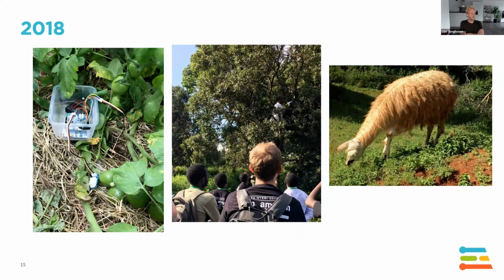Once again, these are use cases we tried to deploy in the conservatory. The one thing we realized was that we figured we were going to do LPWAN connectivity. So we had some base stations, and we figured we'd just put a base station up. I know here in Amsterdam, which is supposedly a pretty harsh RF environment, I can easily do like a kilometer of range. So we figured that was going to be fine in the conservatory. What we realized very quickly, though, is that because there are so many trees, they block a whole bunch of this RF.